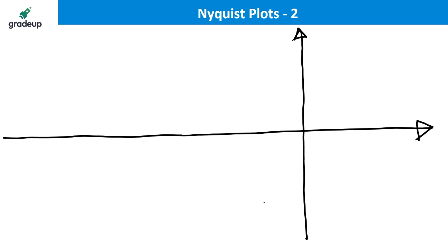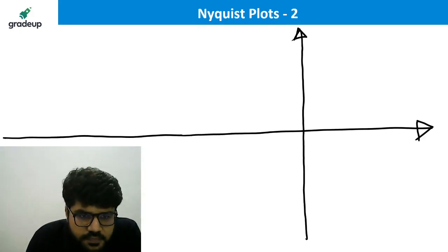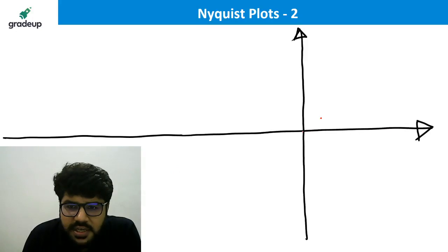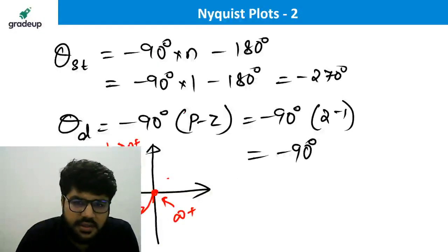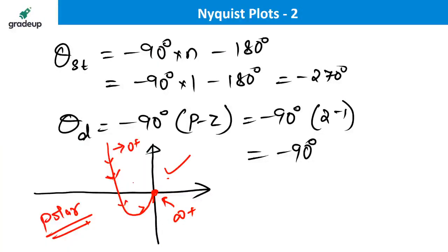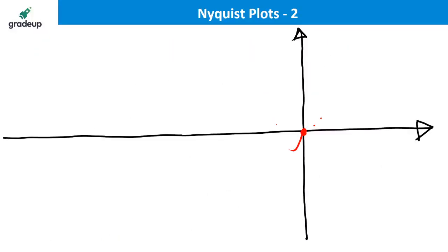First, that same polar plot which I have already sketched, this one. The critical frequency has come. This is known as the critical frequency, on the negative x-axis, that also I have proved to you. So I will just copy this polar plot first.